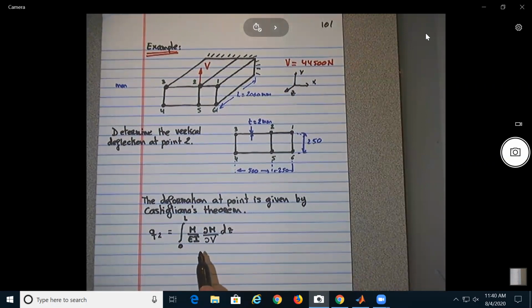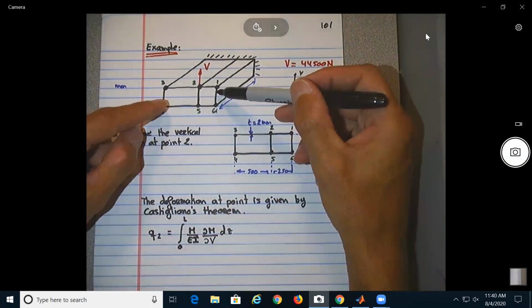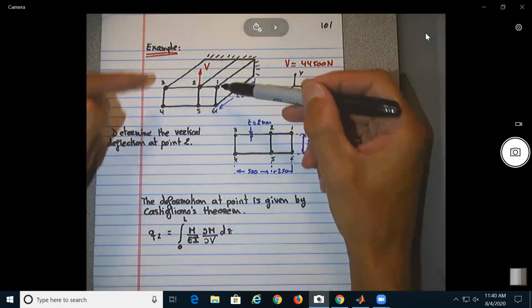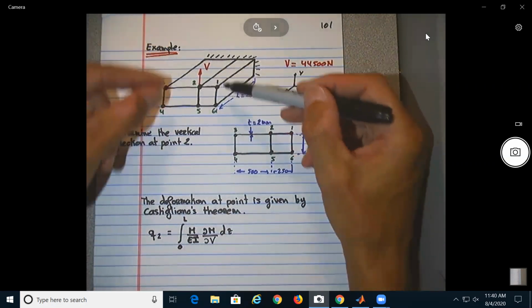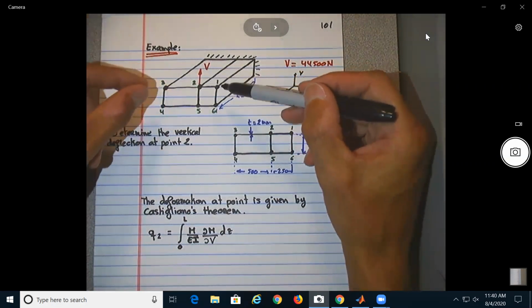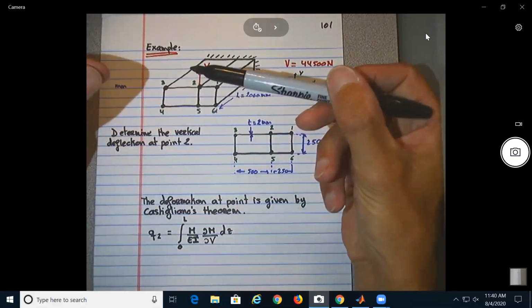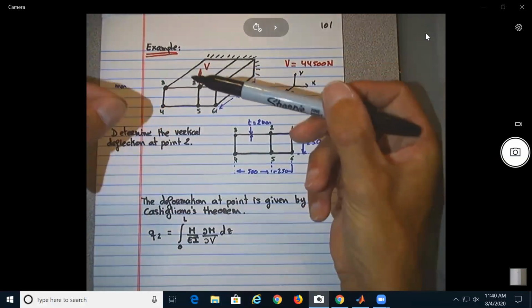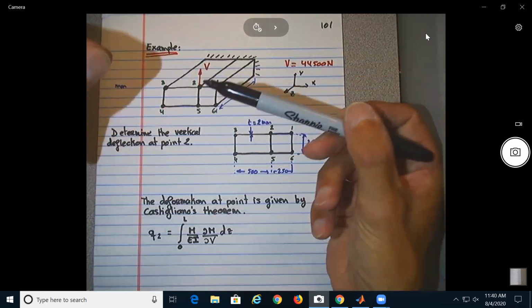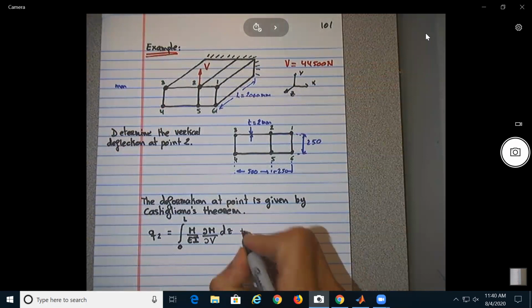So this will be the effect of the bending moment, but then since this one is not symmetric, what's going to happen? This structure here is going to twist, no? So the twist of the deformation due to the shear flows is also going to produce some type of deflection. Does that make sense? If this one moves up, there will be no effect of the torsion, but because this is probably going to twist, the twist is also going to affect the deformation. And that term over here is the most complicated.